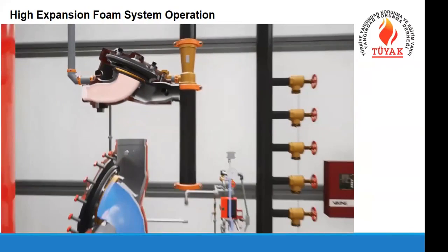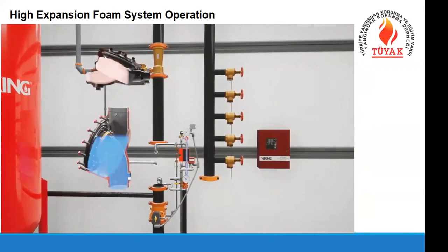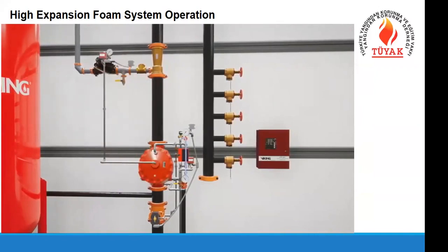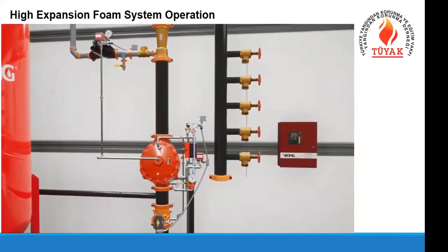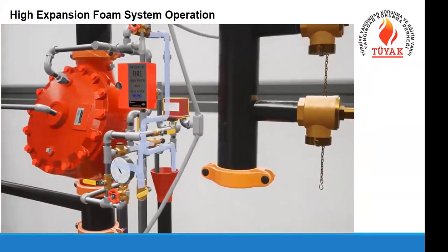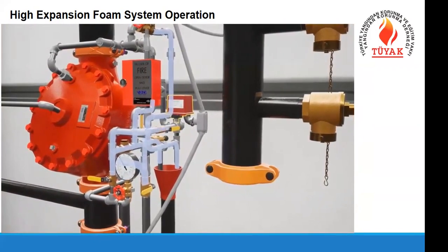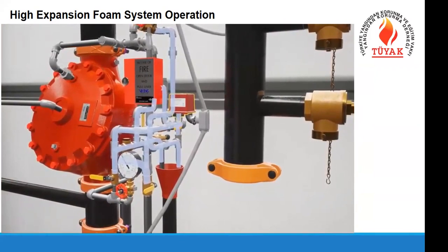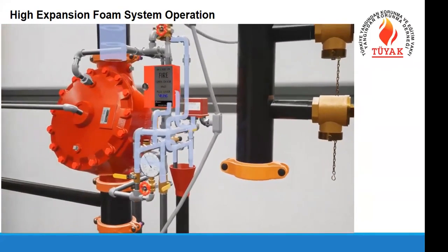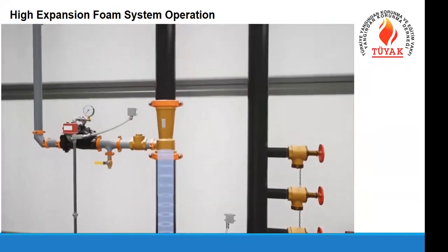After the release of prime pressure, the deluge valve's clapper and the concentrate control valve's clapper open simultaneously. While the next steps happen in parallel, we're going to look at the water side of the system first. Once the deluge valve is open, water will fill the trim and activate the water flow alarm. Water will enter the system riser, passing through the ratio controller.